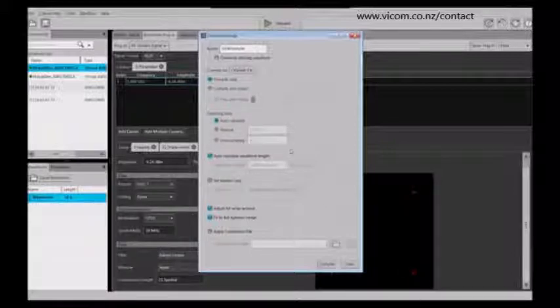And it knows which instrument you're talking to, so it will know what the characteristics are for the AWG that you're using, so that you know that you can't go past a certain frequency. Since I'm using the 2-channel box, you can see it's maxed out at 25 gigasamples. For a single channel box, it would be 50 gigasamples. You can have it auto-calculate the waveform length, and this is dependent, again, on the characteristics of your generation tool. In most cases, you want to leave this automatic.